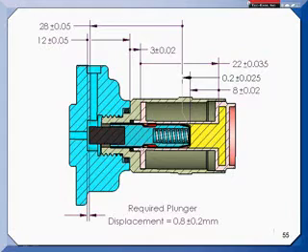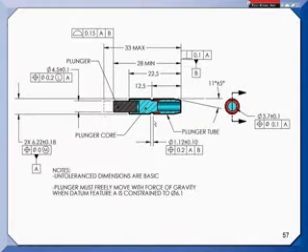And then lastly, if we look at this, it is a subassembly that's purchased, and it is guided or located using this diameter, and it butts up against this surface right here. So we made this diameter A and made this surface B. So following this, what features take away the most degrees of freedom in the assembly? And by doing this, we kept the vector diagram, or the number of vectors, to a minimum.